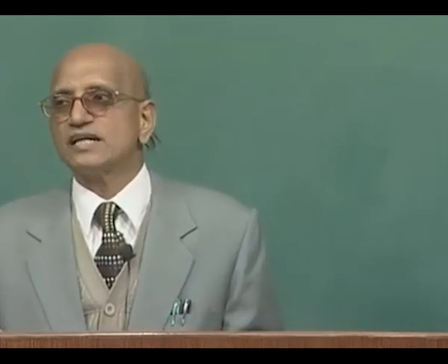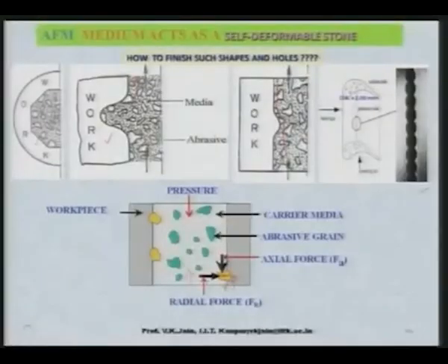Now, since this is the flexible medium, it can go into the fine cavities and finish them, just like the holes we have seen in the earlier slide. Hundreds of holes can be finished in one go, and the diameter of the holes may be smaller than 1 millimeter. Here is another very complex shape.